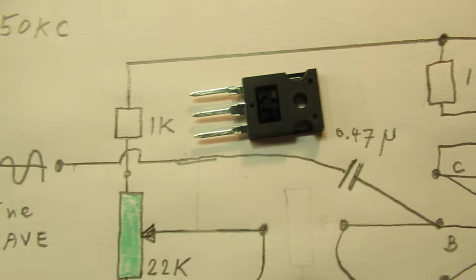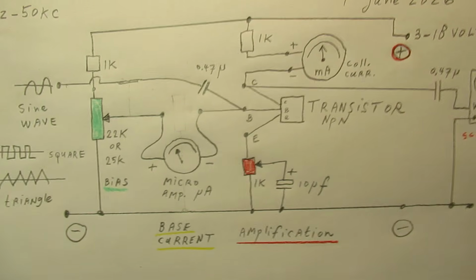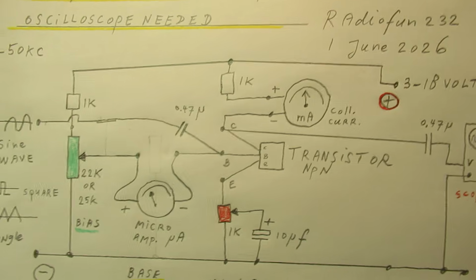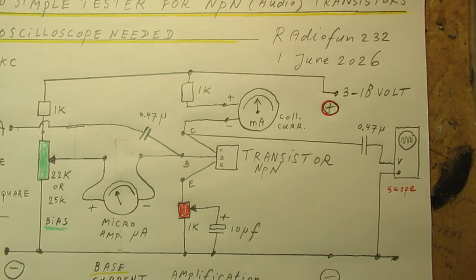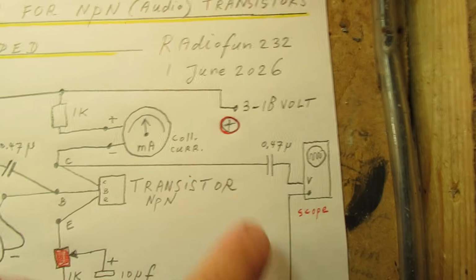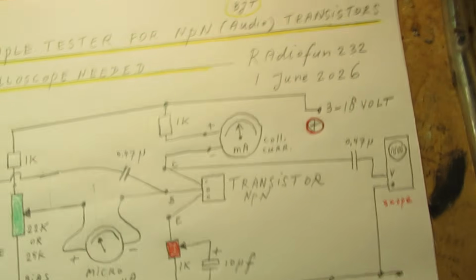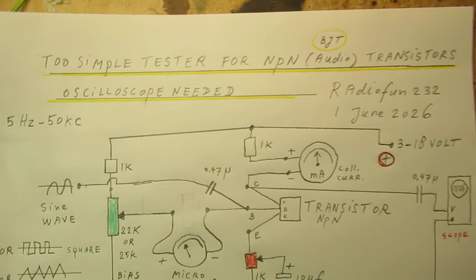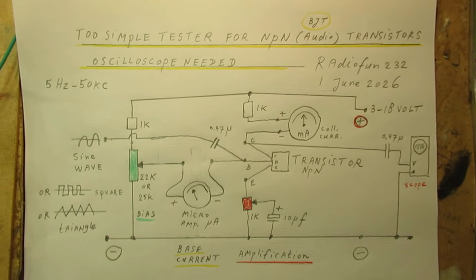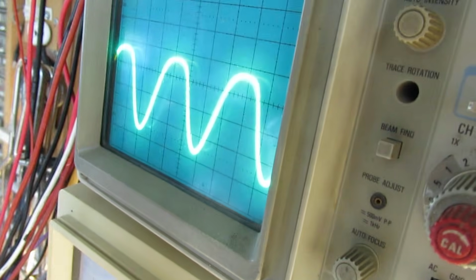Tested this transistor. That is the TIP3055. Tested low noise transistors and normal NPN transistors. Also tested a high voltage transistor, and of course for a high voltage transistor the biasing must perhaps be in another way. And of course there must be a high voltage when you want to test such a high voltage transistor properly, but anyway, it also showed that it worked nicely in this circuit. And of course, when the transistor doesn't function, you don't see that sine wave.